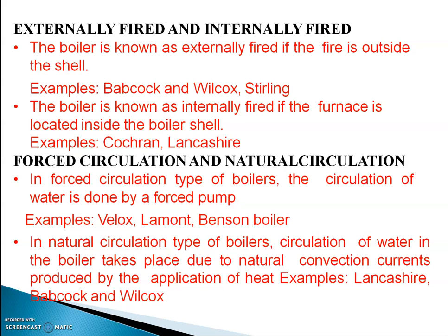Another categorization is externally fired or internally fired. The boiler is known as externally fired if the fire is outside the shell. Example: Babcock and Wilcox, Stirling boiler. A boiler is known as internally fired if the furnace is located inside the boiler shell. Examples: Cochran boiler, Lancashire boiler, Baby boiler, simple vertical boiler or locomotive boiler.